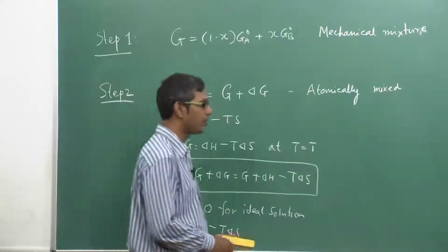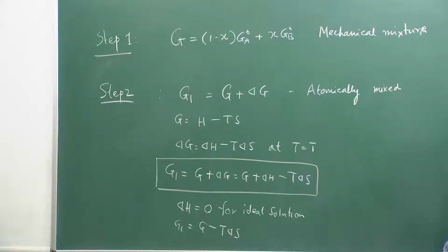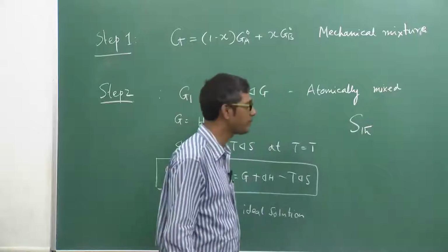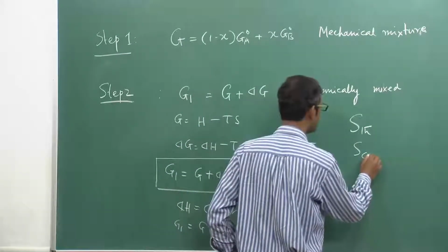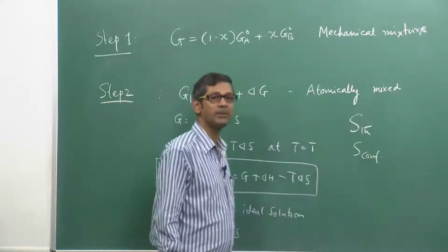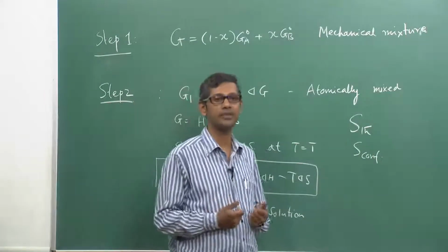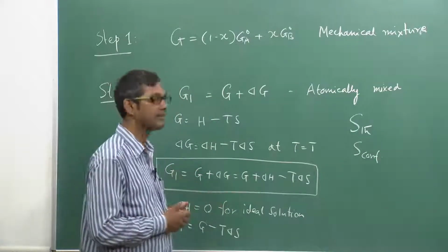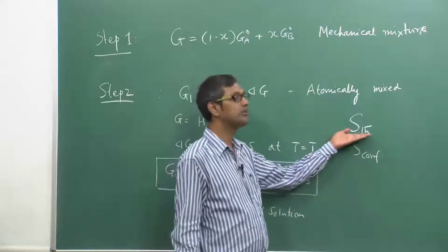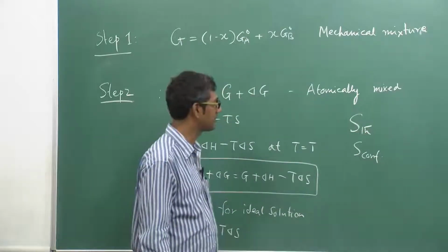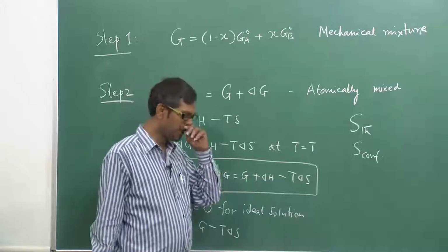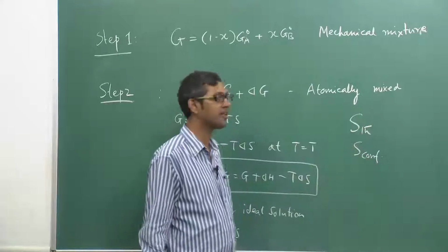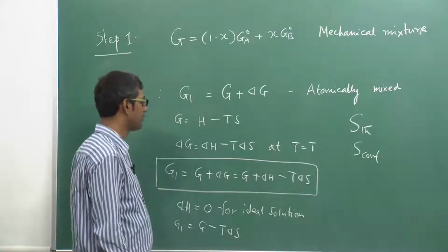Now, as you know, entropy has two important parts. One is the thermal entropy, or what is known as the vibrational part of entropy, and the other one is known as configurational entropy. So, what is vibrational entropy? If I heat a system, the atoms start vibrating. Therefore, the energy levels of atoms will have different characteristics, and that contributes to entropy because of the thermal aspects. Normally, in metallurgical thermodynamics we ignore this part because it is not a substantial amount in the case of solutions.